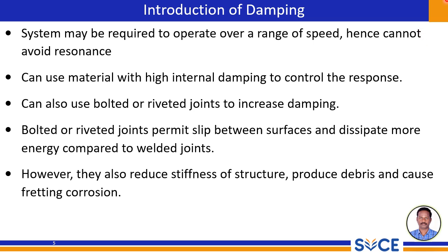So, introducing damping is very crucial when resonance cannot be avoided. We can achieve this through material selection or by incorporating specific joint designs. However, it is essential to consider the trade-offs, particularly potential reduction in stiffness and the risk of debris and corrosion.